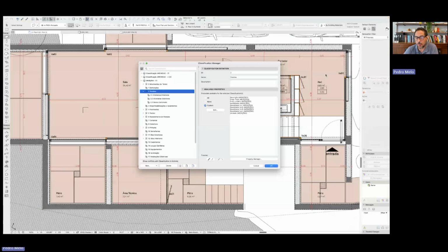And of course, each one of them has some properties attached. I can explain a little bit about this, but this enables us to go really fast. In a house like this, we can do quantity takeoff in an afternoon. Okay, it's not coming straight out from Archicad, but it's one person with a model and the other one in Excel, just copying numbers and writing up the descriptions, etc. The goal would be in the long term to do everything from Archicad, but it's still an ongoing process. For simple stuff, it's possible. For big stuff, it's a little more cumbersome.